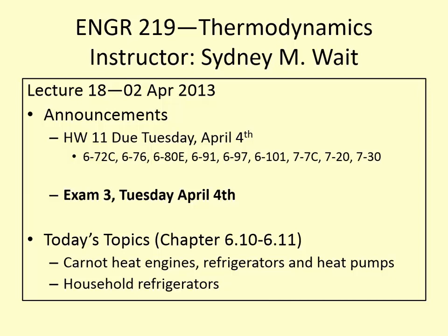So if we're looking at the Carnot cycle as the idealized cycle for a heat pump or a refrigerator or a heat engine, then when we have a real device and we compare it to that cycle, we can say, oh man, I'm only getting 50% efficiency, but the Carnot cycle maximum efficiency is maybe 55%. So really it's not as bad as we think. Sometimes seeing really low efficiencies makes us worried, but in reality when we're converting heat to energy or to work, we don't get very high efficiencies anyway.